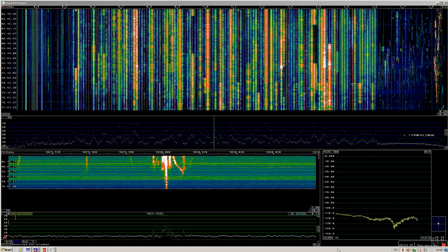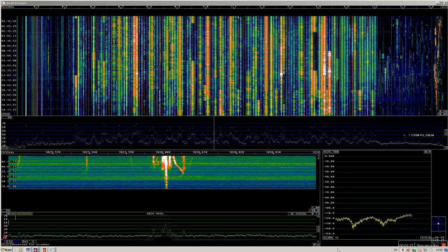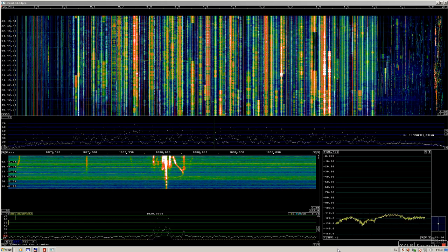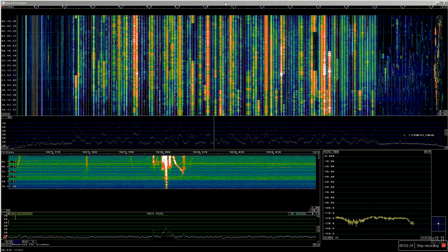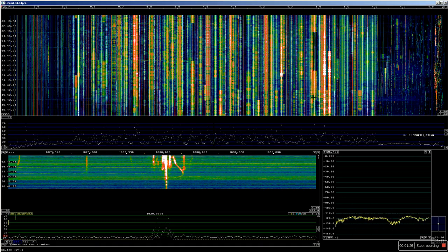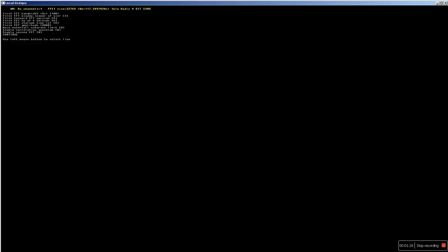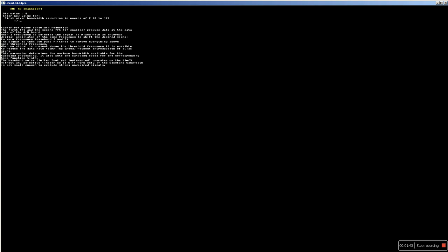It is possible to look a little bit in details on this. To do that, I just press X after making sure I have focus on Linrad, X, and then parameters, and I leave the first FFT unchanged, but reduce the baseband bandwidth from 8 to, let's say, 11.